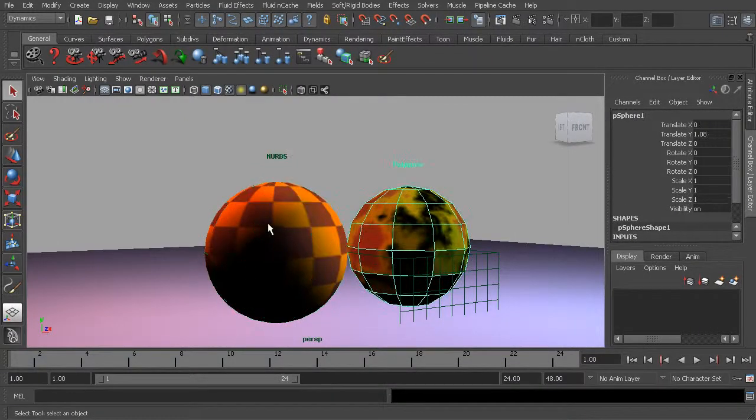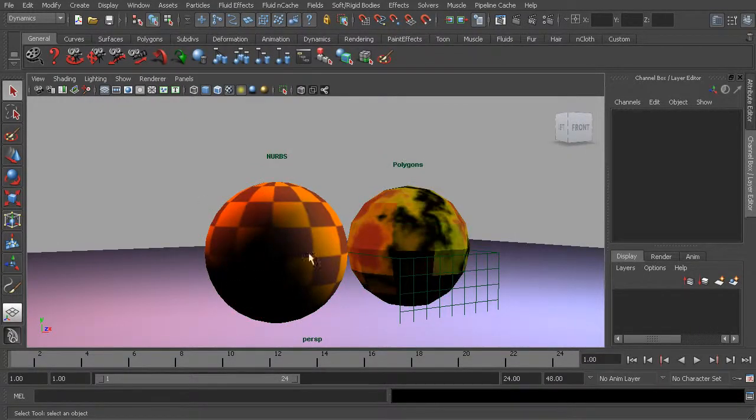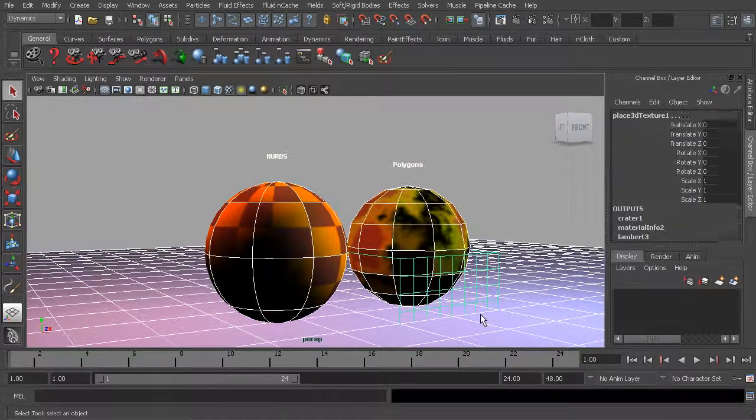Now, if I press the Control key on my keyboard, Control acts as a pure deselection mode. So you can see as long as I press and hold the Control key, it's only going to serve to remove objects from my selection. Now if I press Control and Shift at the same time, this is used purely for adding to selections. So you can see if I press and hold Control and Shift at the same time and try to make my selections, it will only add.